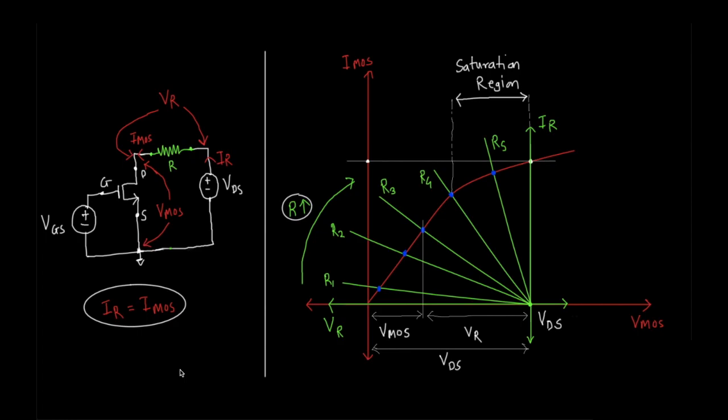Well, the value of current will also change, which we will try to find using the graph. Let's look at the Ids-Vds graph now. As seen, now the Ids current is set by VDS. Similar to how we created that graph for voltage and current through a resistor, we can create a similar embedded plot here. Just that it will come on the x-axis, not the y-axis, because we are controlling the voltage VDS here and not the current ID. Now where will the origin be on the x-axis? It will be right on the value of VDS.